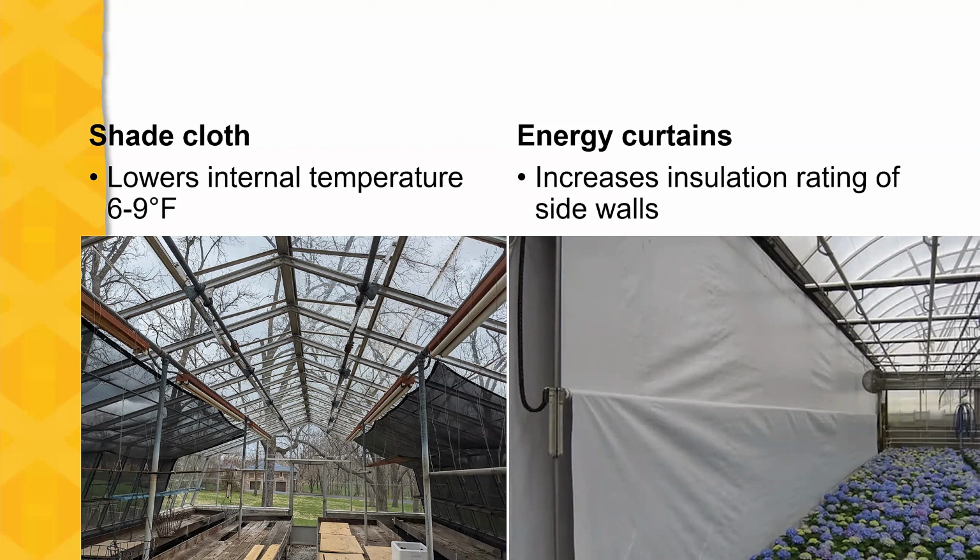And just think about the greenhouse or the high tunnel covering and the structure, the beams and everything. These are already blocking 20%. So if you want to have 50% radiation or sunlight inside here, and these are already blocking around 20% of the sunlight, you need to get a shade cloth that is rated at 30% shade. And that's going to give you 50% shade inside here, right?